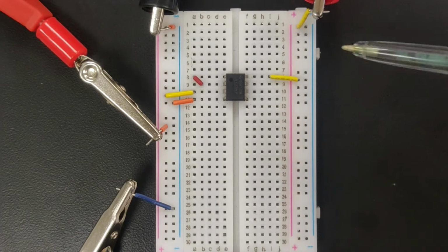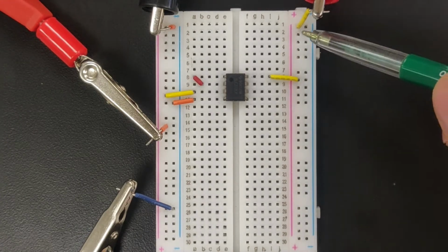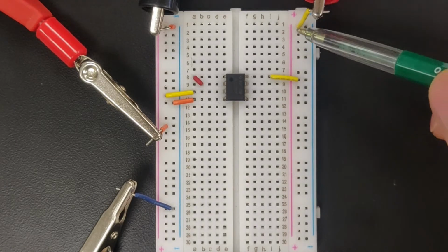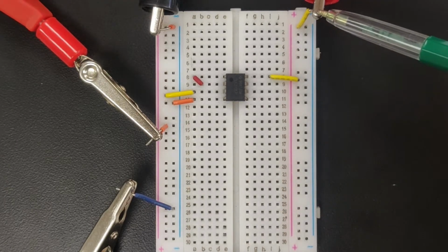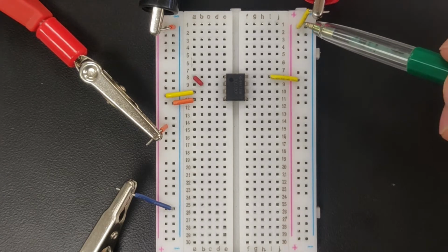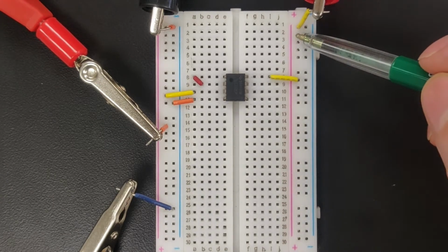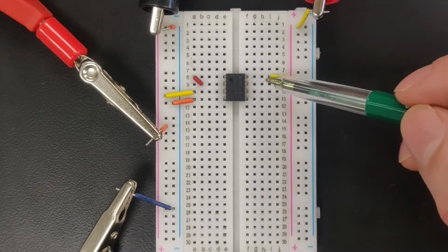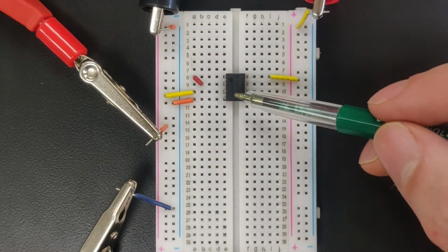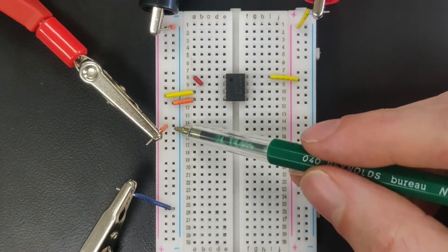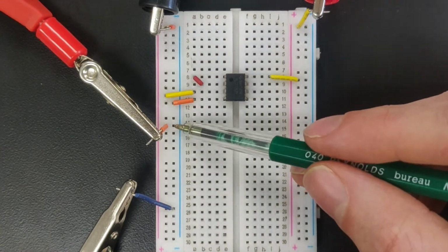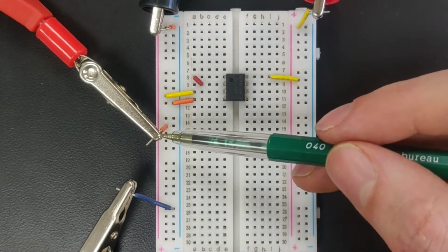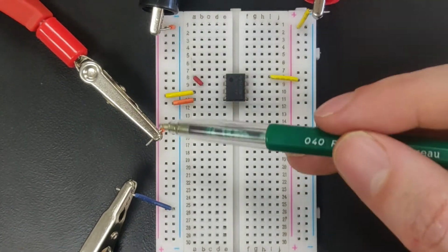All right, so like I said, this is for our DC power supply, and that's what this lead is coming from. So we have our DC current coming in, jumping from this row to this pin, and eventually it goes through our op amp and out through the ground pin, and then this blue column is ground. Over on this left red column, we have our AC input, coming from our function generator.